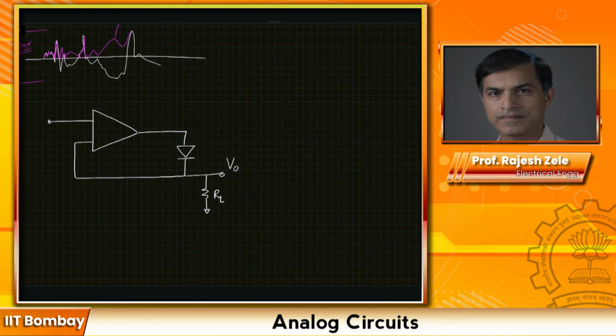So first important thing is, what would be the signs at the input of the op-amp? We should be able to tell that this op-amp should be in negative feedback mode, and for that the diode needs to be on. So the diode D1 is on, and if the diode D1 is on, then this terminal needs to be negative, this terminal needs to be positive.